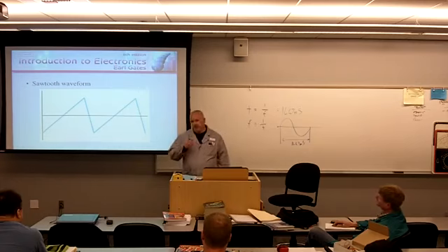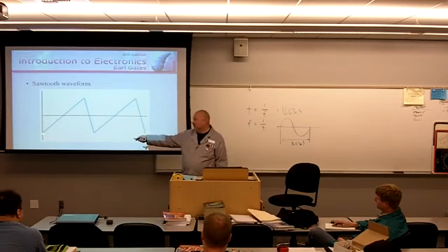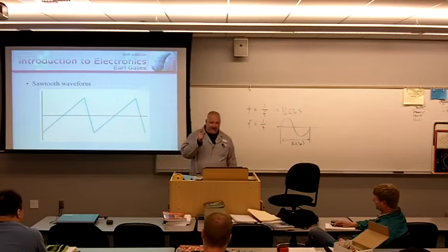Same thing with your oscilloscope. That's how an oscilloscope works. When you get a display up, basically what that display is, is that beam getting pulled left to right across the face of the oscilloscope. It's a sawtooth generator that's creating that. Low voltage to a high voltage, and then rapidly resetting it faster than the naked eye could perceive it.